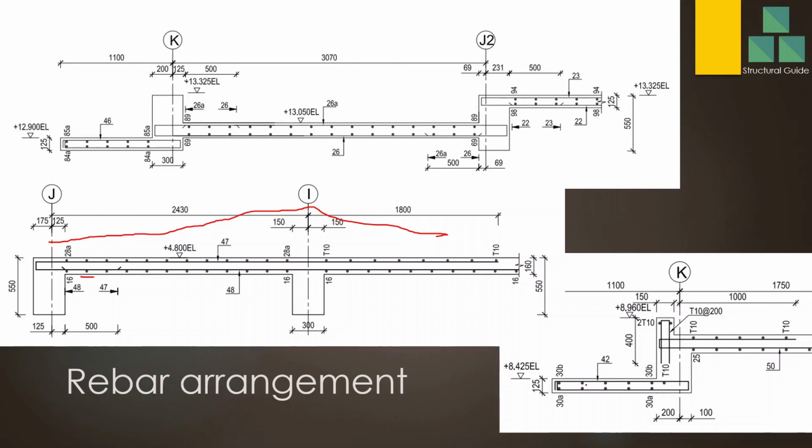Then the top reinforcement of the cantilever is restrained well. Those things you can use in the standard methods or the correct method. It is not a must to have that distribution bar always, but if you have a fairly large cantilever, it's advisable to have a distribution bar tied to the link like this.